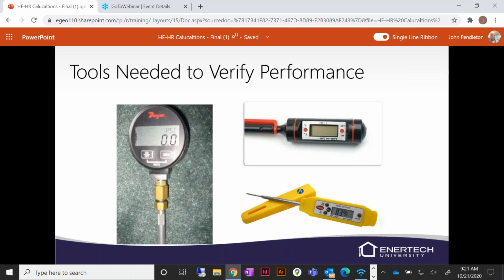The old style temperature thermometer there, the black one, is the old style. It's got the thicker shaft on it. It will work. You may need to use some type of water soluble grease to get it into the PT port without stretching it out.